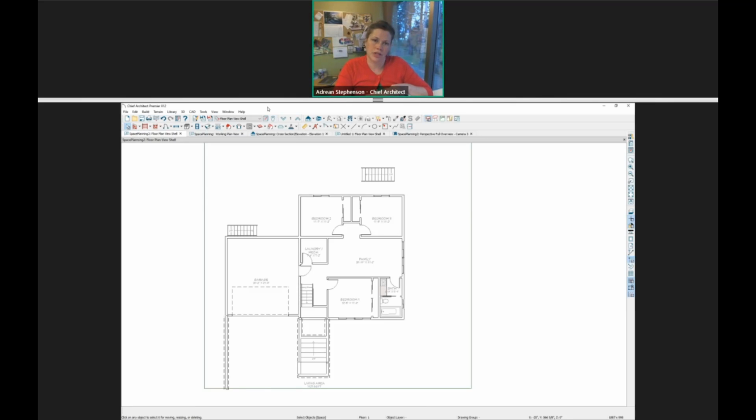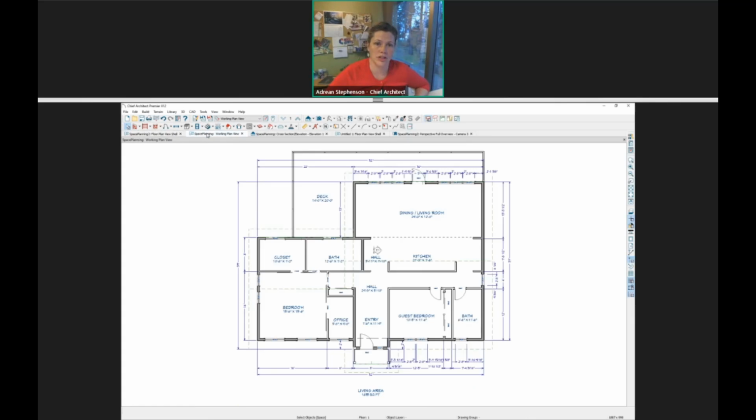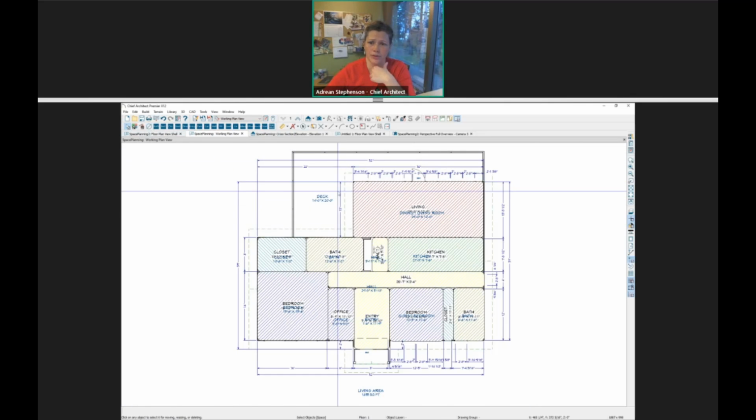There's a few ways you could do it. If you wanted to do that with the space planning tool, before you get the final walls inserted into the projects, you can always turn your layout boxes on after the original construction. So let's say on my main floor here, I want to come back through and revisit those space planning boxes. I can toggle those back on and access them again, so I can move them around. That won't affect the walls that have been created. So once the walls are created, they're kind of there.